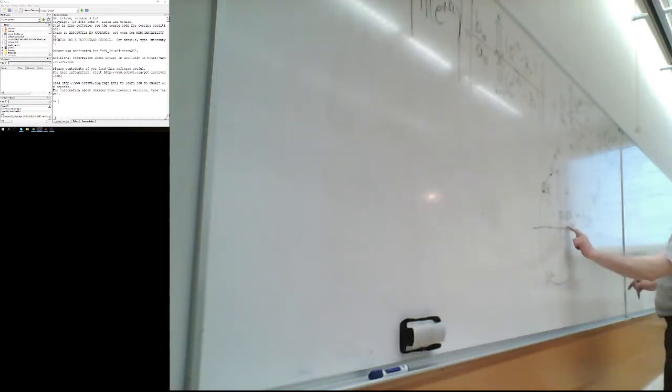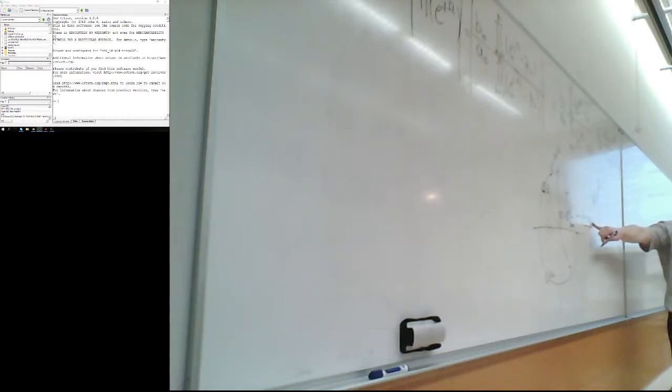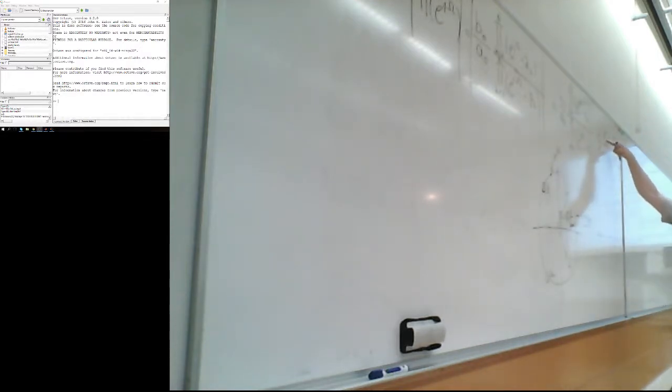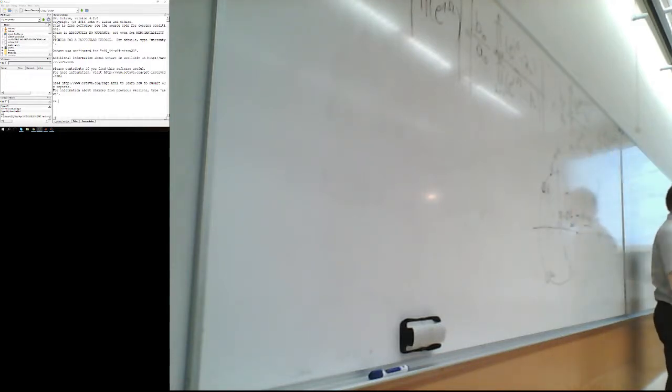At that point, 3 pi over 4, which is 750 hertz, this is 0. The distance, because it's exactly at the same point as the zero on the unit circle, becomes 0. So the amplitude response is 0. In our graph, it was logarithmic, so it means it has minus a few hundred dB.